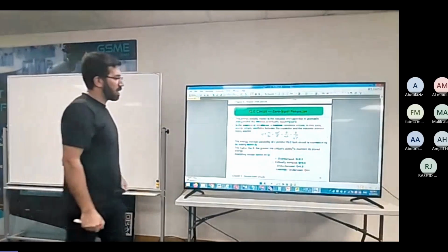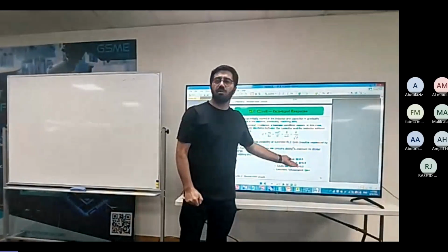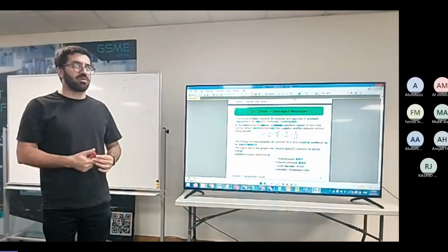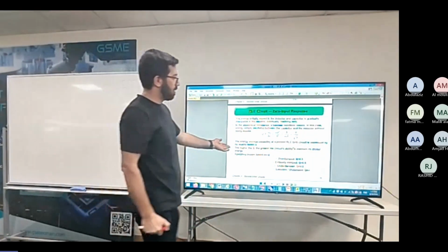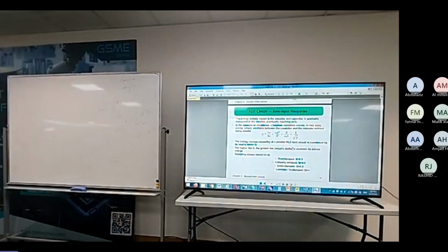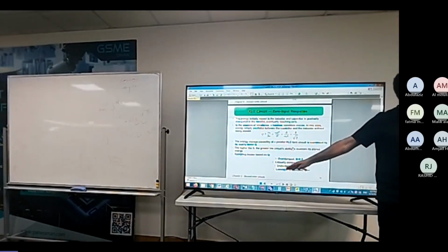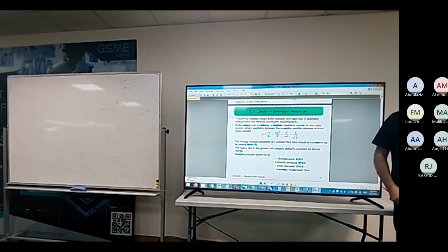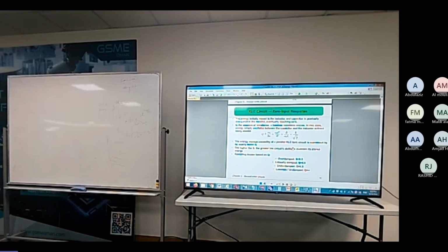If it is overdamped, that means we have a big loss or small resistor, so the circuit cannot store the energy. If we had a lossless circuit, we are storing all the energy we got at the beginning. The bigger quality factor means we can store more.